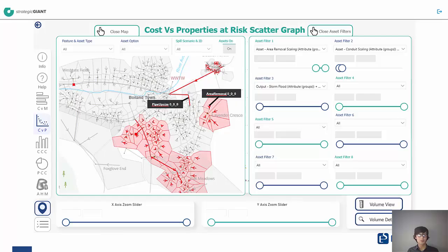So say, for example, we're in a meeting with some stakeholders and we find that a particular SUDS area removal option will be particularly challenging to build, let's say this region here. Well, as the optimization has run large numbers of designs, it's likely there should be several alternatives already available in the dataset which don't require that particular asset. So we can use this reporting tool to apply a filter to take that option out of the set of results and show what's left.